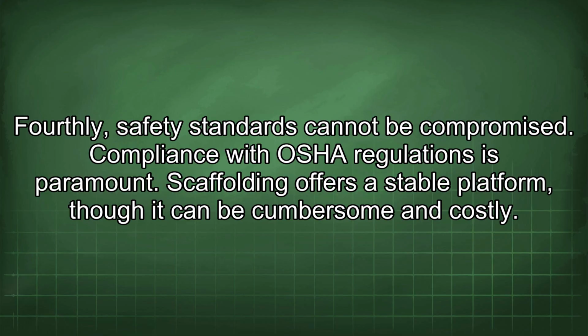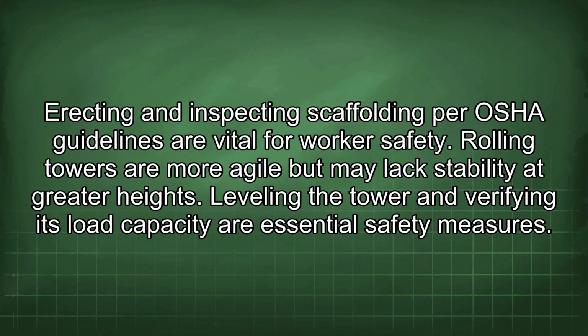Scaffolding offers a stable platform, though it can be cumbersome and costly. Erecting and inspecting scaffolding per OSHA guidelines are vital for worker safety. Rolling towers are more agile, but may lack stability at greater heights. Leveling the tower and verifying its load capacity are essential safety measures.